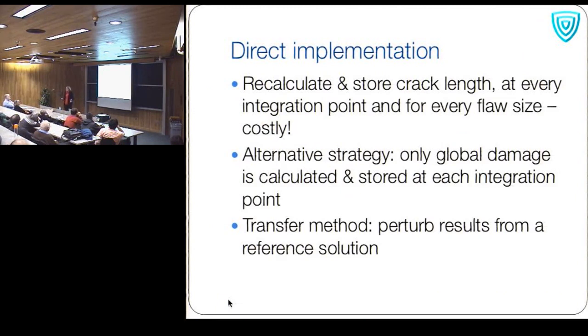These all have kind of the same shape. We're reflecting the same physics. So what we thought about was, why don't we just do one run, stress versus strain, then figure out in that one run what the gradients are with respect to the things that change from one integration point to the next, and just use a Taylor series approximation to the results.